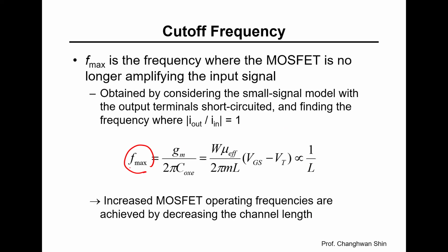Number one, Fmax is inversely proportional to the square of the channel length here. And this explains why reducing channel length dramatically improves the frequency response. Making the channel length half enables you to quadruple Fmax, which is similar to how reducing a car's weight significantly improves its acceleration.